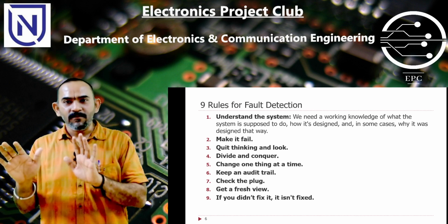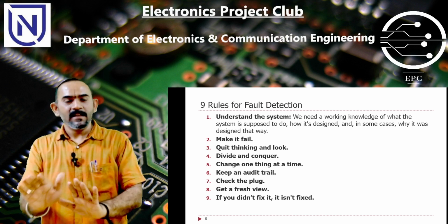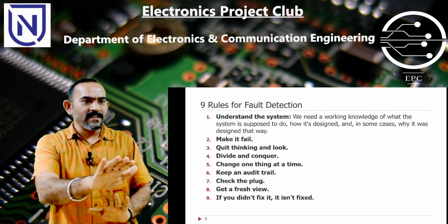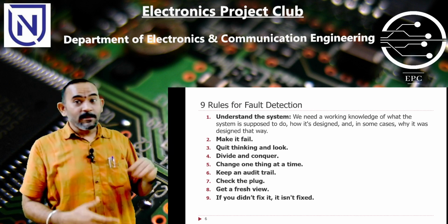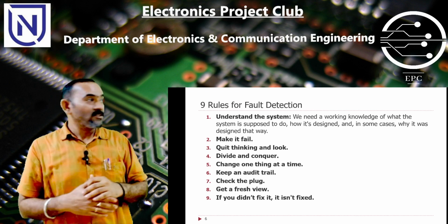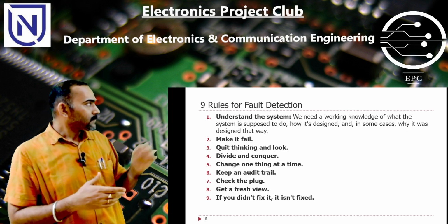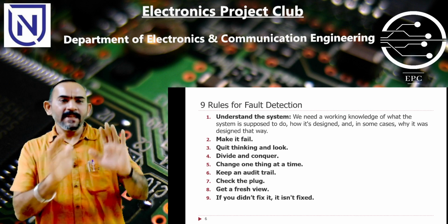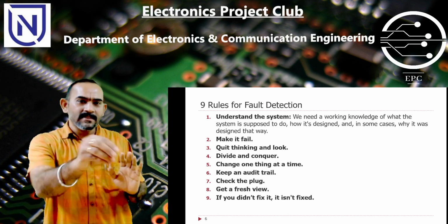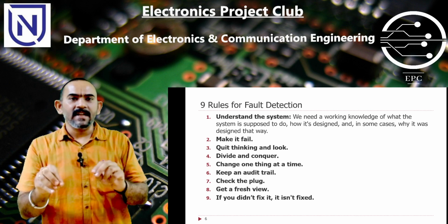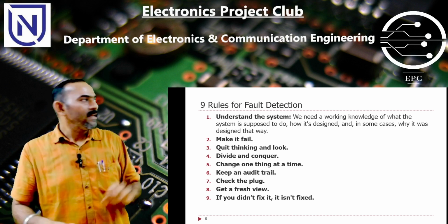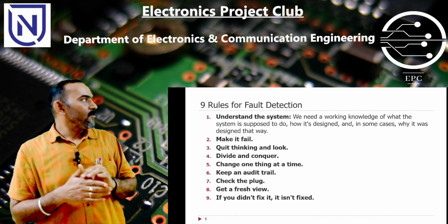So we have to stop sometime, decide that this many possibilities I will test first, and then do it. The steps look trivial, but they are actually what is followed when we try to debug. So we have to stop thinking at some time and start doing: start checking the devices, start checking the voltages, start probing. We have to go and work in the lab.